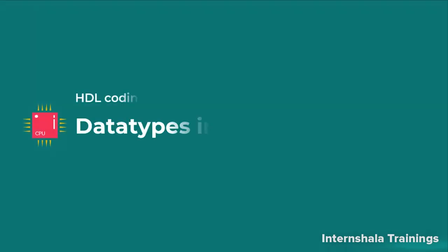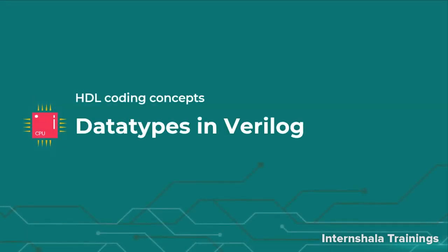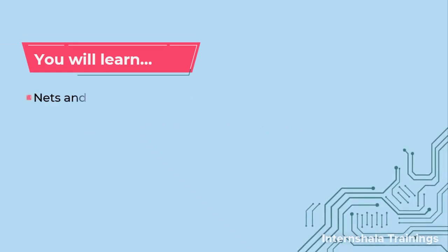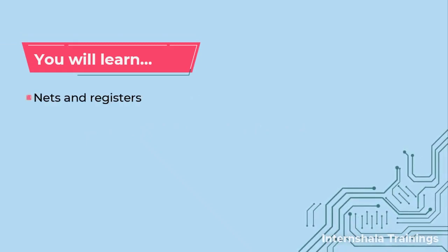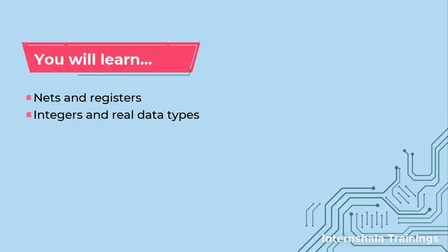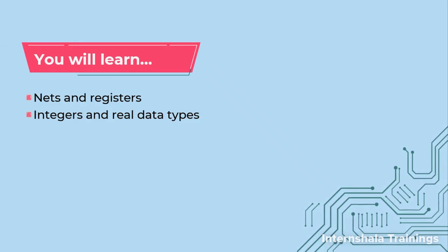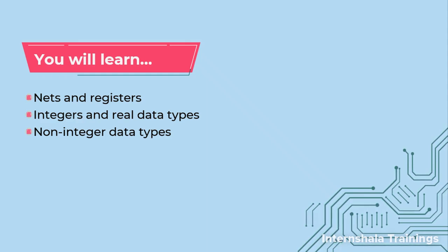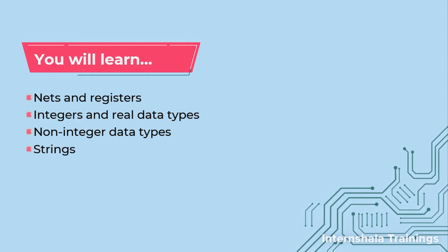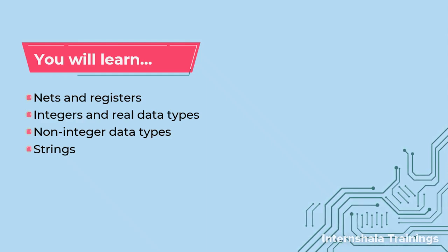Hello students, welcome back. So now we are going to talk about different data types in Verilog. In this video we are going to talk about what nets and registers are. We will also talk about integers and real data types, non-integer data types also, and we will also touch on what strings are in Verilog.